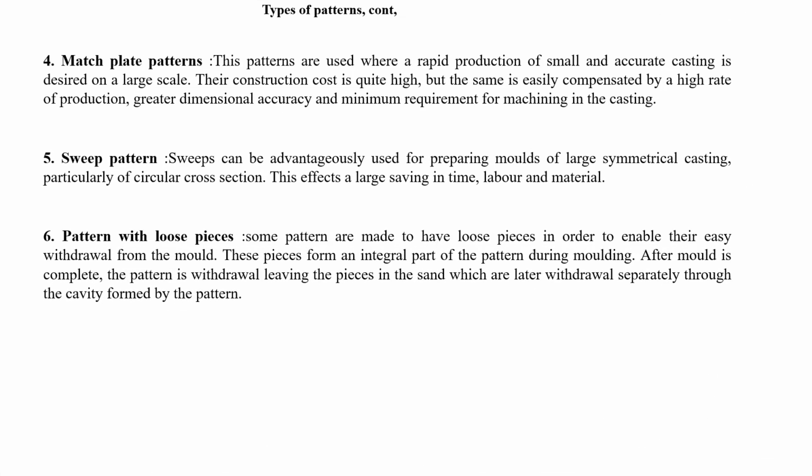We have also what we call the match plate pattern. This is used when greater dimensional accuracy is required, and when minimum machining is required.